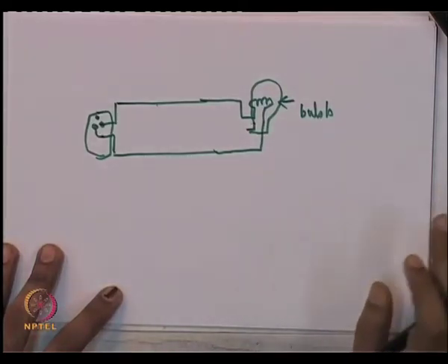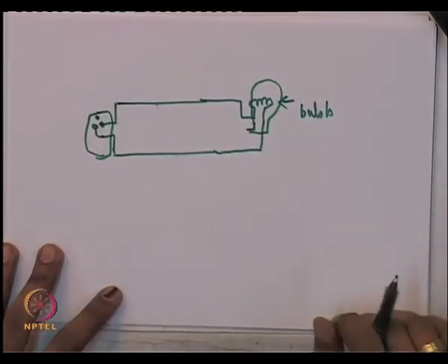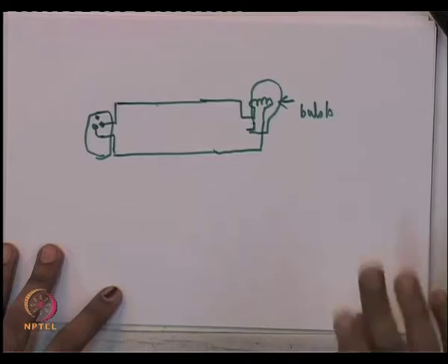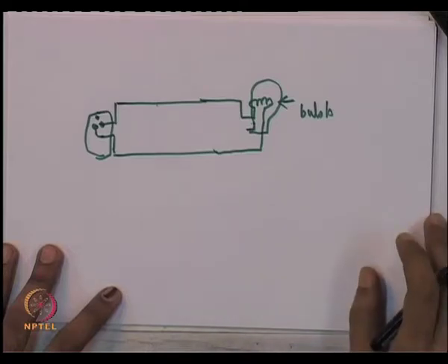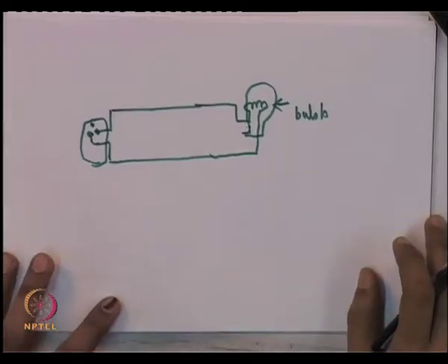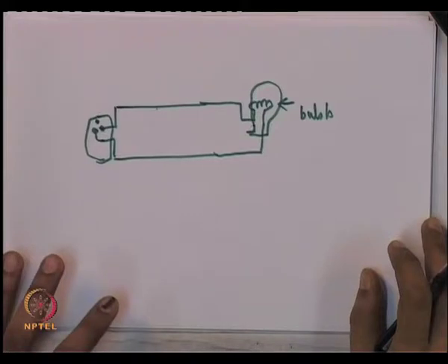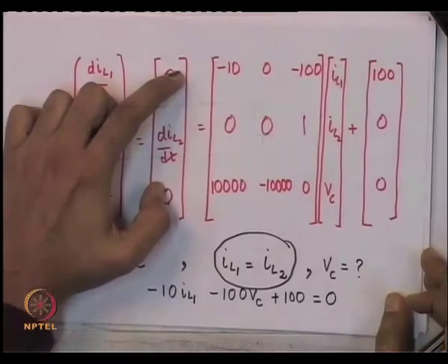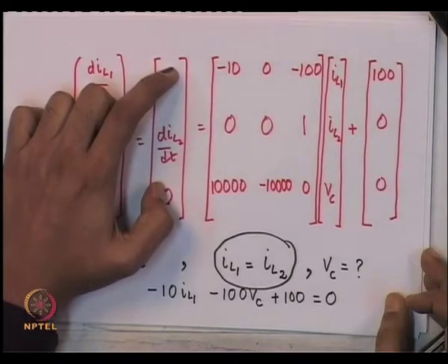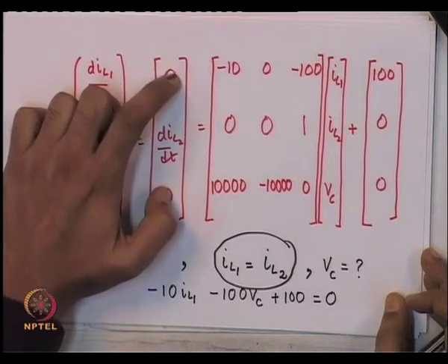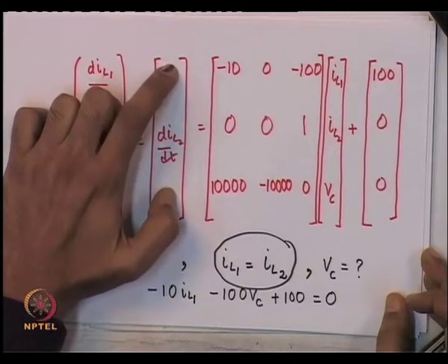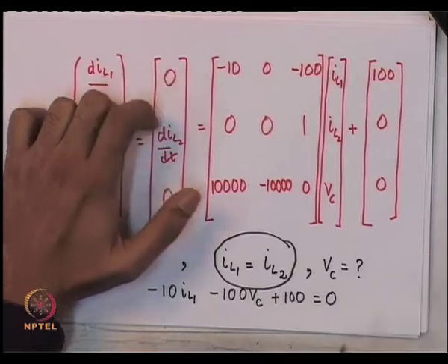But usually we may not be interested in those fast transients. In such a case, remember, you can make an approximation. You can neglect the dynamics associated with the fast transients by simply taking the state equations and setting the right hand side, where we write the d by dt's, equal to 0 in those states which we think are associated with the fast transients.